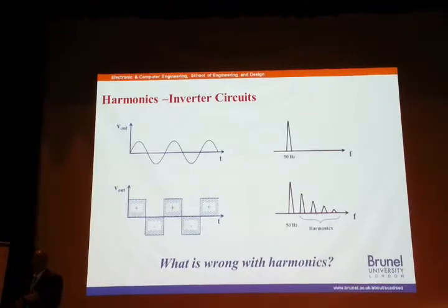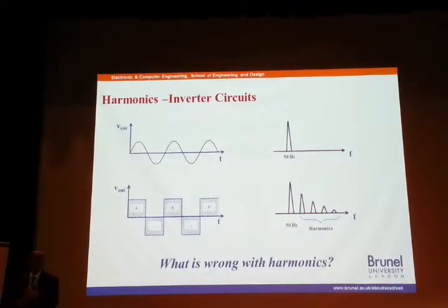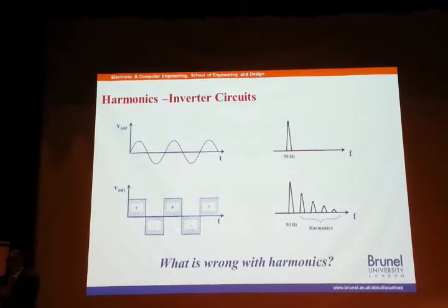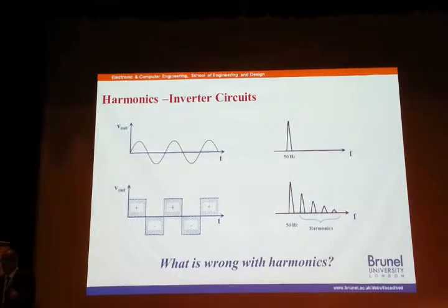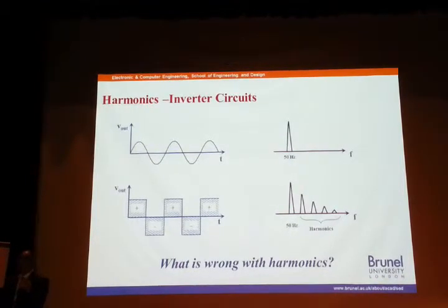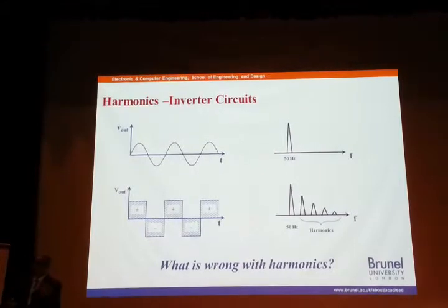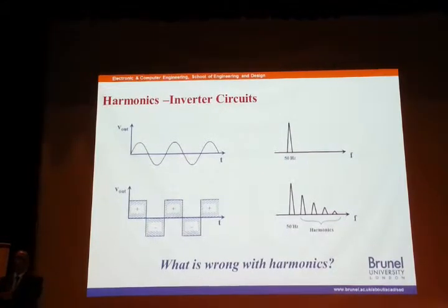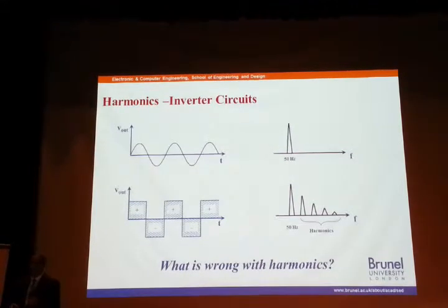But you're absolutely right. What we can do, we can play within the inverter circuit. There's something which we call a multi-level inverter, and then we can improve the performance, but we cannot eliminate the harmonics completely. This is the nature of the switching operation itself, okay? So we need to filter it out. We need to have some sort of harmonic filters as much as we can.